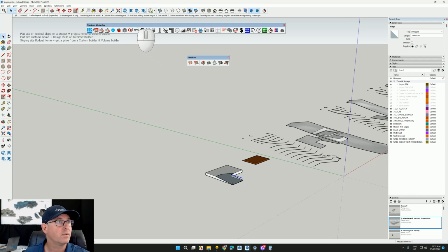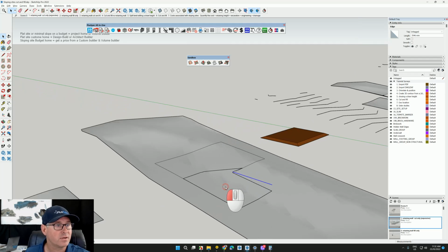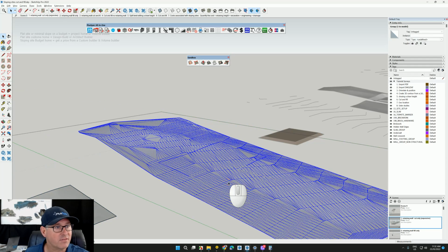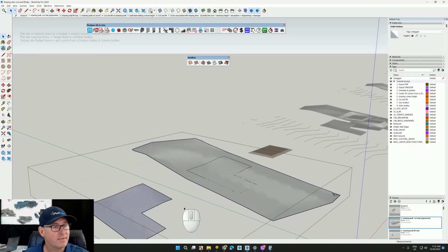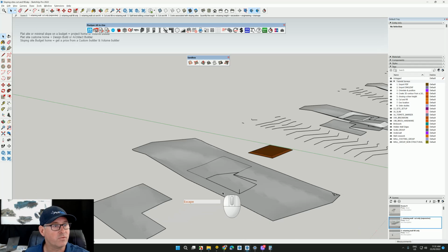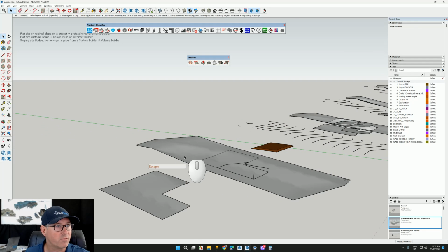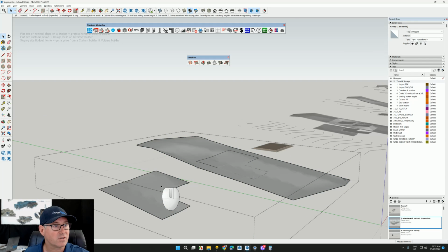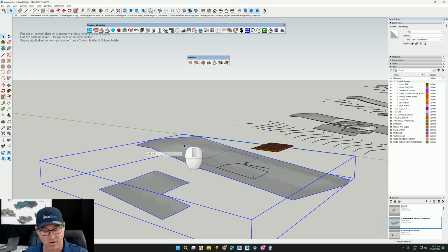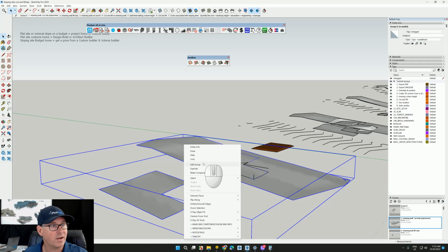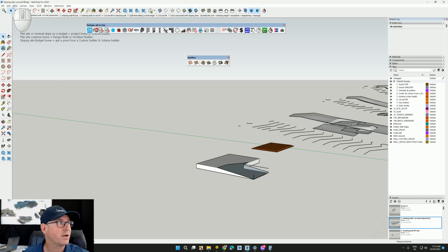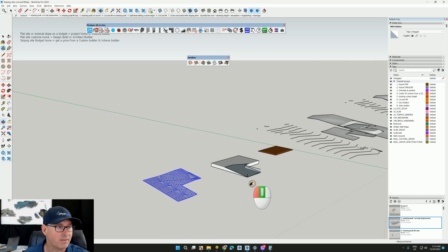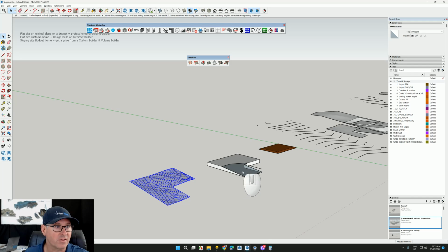Go to all. See all. You notice that I have that face there, so I already have this face here. Alright, so I could actually move that back over to help me move forward. So if I go inside of here and go copy, Control C, and then I go to here and hide it, I should right click hide, I can go edit paste in place, and I can move that back 15 meters to cover the area that I've actually cut.